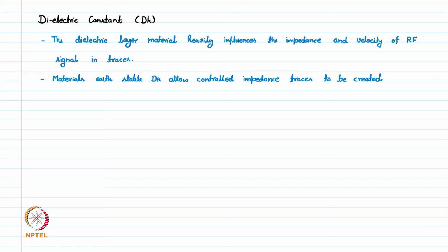So if we have a material where the dielectric constant is very stable, it does not change with temperature or does not change with the frequencies, that allow us to make traces with very controlled impedances.